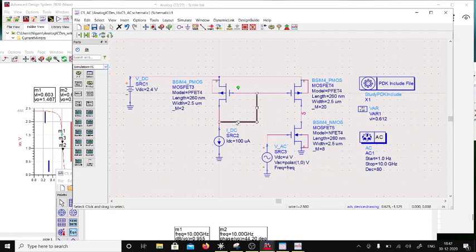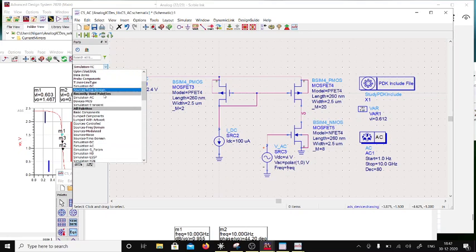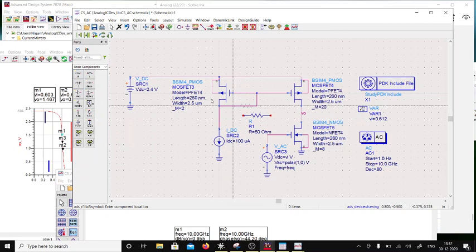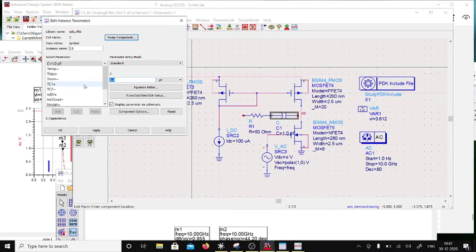I'm not going to do that here; I will go into a separate session on compensation. Here I'm going to do a lead compensation, and that too I can derive, but for now I'm just going to give you a direct lead compensation. So I am going to choose here. Now these capacitor values can be tuned. So I'm going to start with 50. Sorry, this is 0.5 picofarad. So I'm going to start with 0.5.